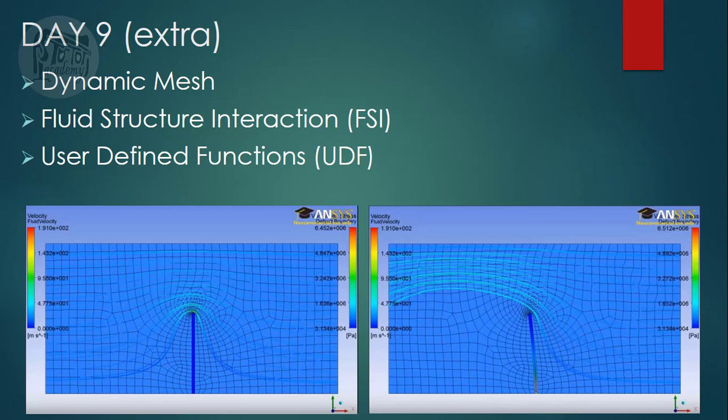So let's say we have a wing, and when the aircraft is flying at full speed, there will be a deformation of 3 degrees. So what we do is a pre-twist of -3 degrees. This way, when we are at full flight speed, the total deformation will be 0, because we have a pre-twist of -3 and a twist of 3 degrees due to the moment. We don't have to add weight to make the wing too rigid. It can be flexible, and we will accept the deformation, but we have to know that in the design we have a pre-twist. So the finite element analysis is a good way because it has an accurate solution. It is excellent in dealing with these types of situations and problems.